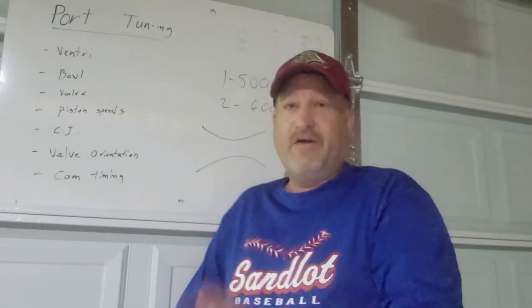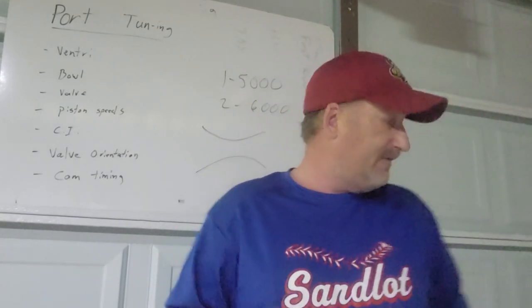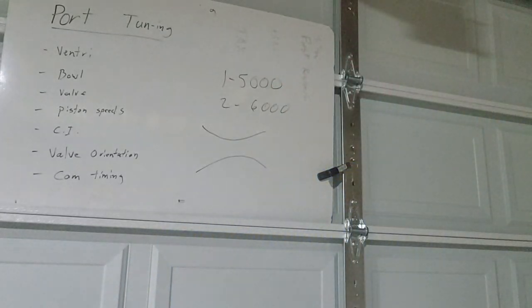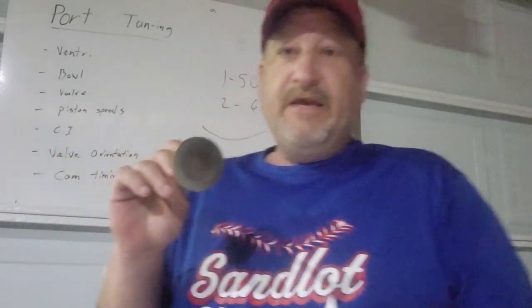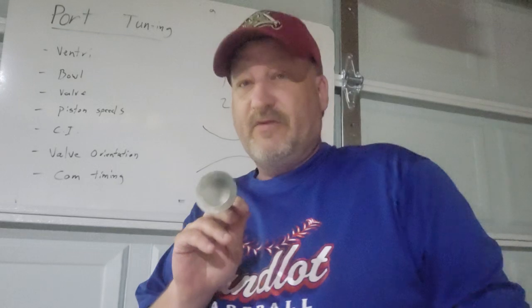Okay. Now the valve also affects port tuning. Depending on the face of the valve, let me grab one here. Even the valve face right here, the cup portion, will dictate the tune of the reversion.